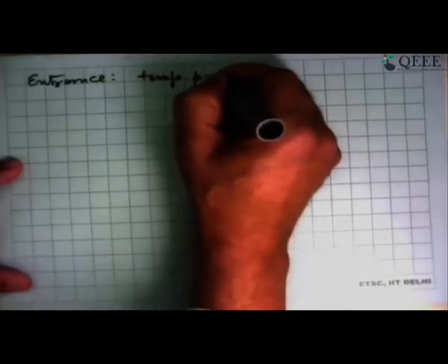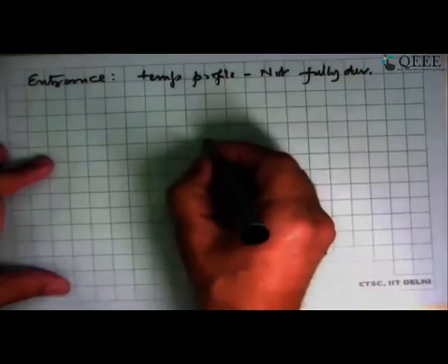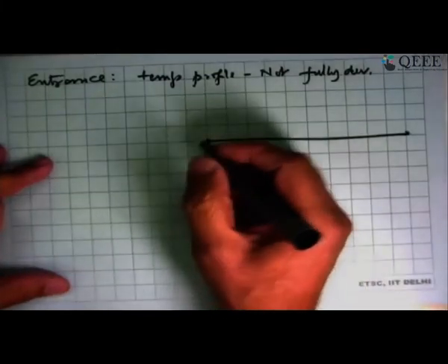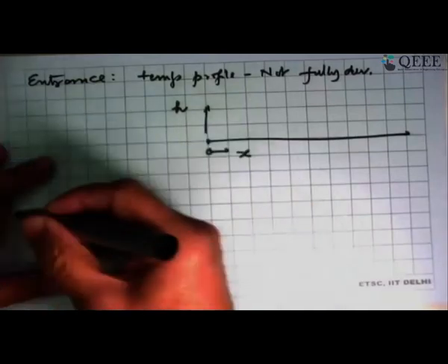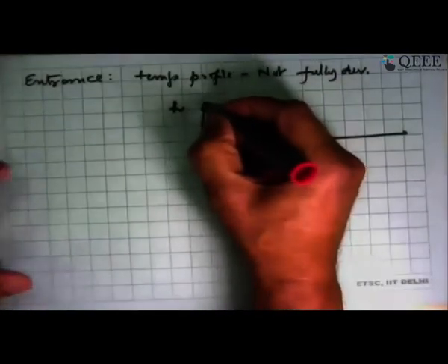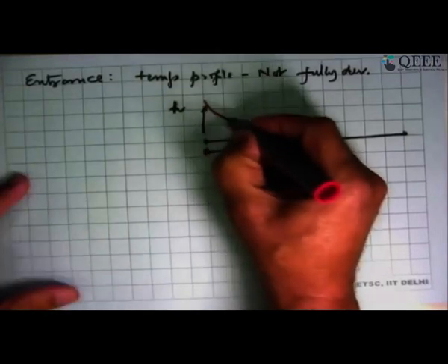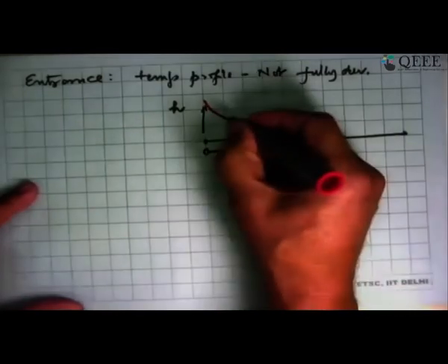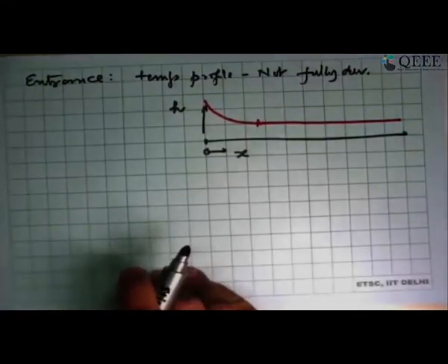So what it means is that we now have two portions. The entrance portion, where the velocity and temperature profile is not fully developed. So in that case, h is not going to follow this trend, and if you have to plot that along the length of the tube, so this is the entrance region. If you are plotting h on this axis, and this is x equal to 0, here the flat plate boundary layer tells us that at the entrance the heat transfer coefficient is very high. As the boundary layer builds up, it will decrease. So in here it will follow that. But what this other expression has told us is that after a while, when the flow has become fully developed, say at this point, h is constant. This is a nice thing to know.